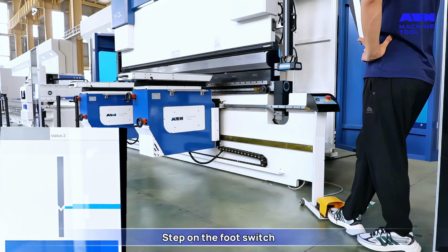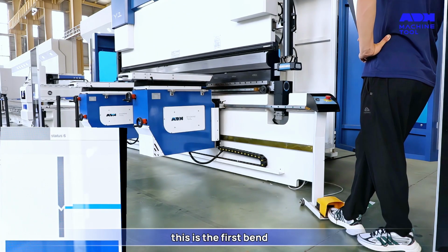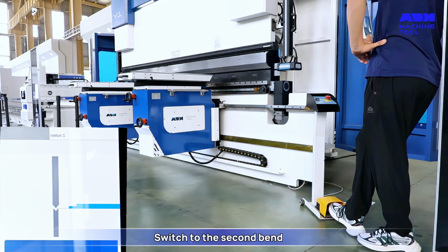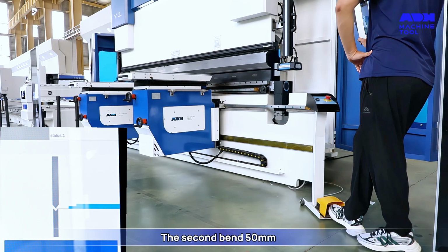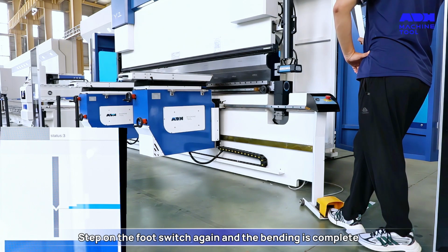Step on the foot switch. This is the first bend. Switch to the second bend. The second bend, 50 millimeters. Step on the foot switch again, and the bending is complete.